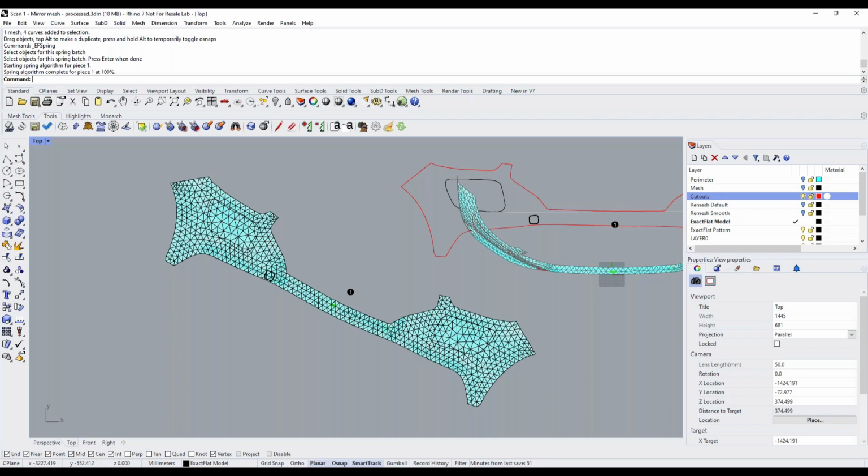Okay, next question. Is ExactFlat used in the metal forming industry? Are there material settings already available for this? So the answer to your question is yes. If you are making metal or thermoformed objects, you can use ExactFlat. There are a couple of other considerations. First of all, you need to get your material tested for the type of stretch. Metals are generally isotropic, so they will stretch the same in all directions, but they may have a thickness.